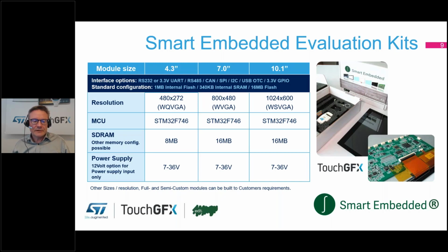As you can see on the slide here, we have made a standard module with a 4.3-inch display. We have made another one with a 7-inch display, and we have one with a 10.1-inch display, all featuring the STM32 F7 series MCU from ST Microelectronics, and with the TouchGFX GUI framework to present the graphics. So it's a very agile and smooth system that we have put together here. We have a question.